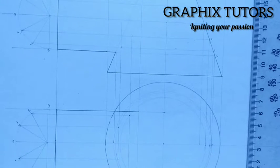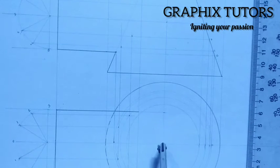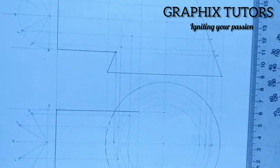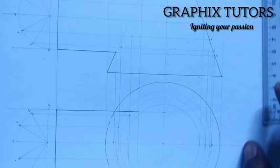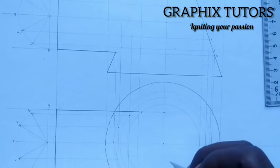and I'm going to place my compass on this point to the point 3 here, the line of 3, so that I'll be able to draw my circle 3. So where line 3, you see this line here, I will extend it to that point. So this is where line 3 meets circle 3, because that is circle 3. So that's point 3.